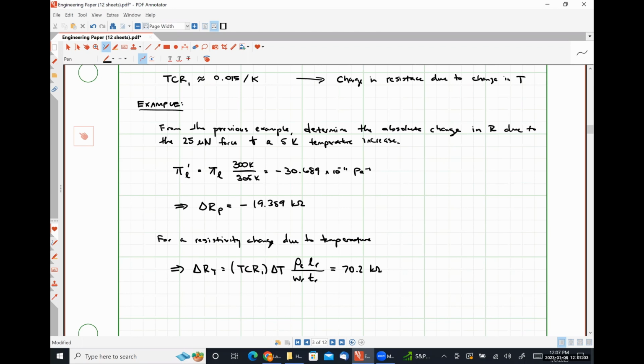We're going to talk about that at the beginning of our next class period. But effectively, if we use ratiometric sensing, the temperature dependence cancels out, because if everything increases by the same amount due to temperature, temperature is no longer important, at least to a first order approximation. So we'll go through ratiometric sensing using resistors, then talk about power consumption, and then do a little bit of noise analysis, and then we'll be finished with this and move along to piezoelectric sensing on Monday's class period.